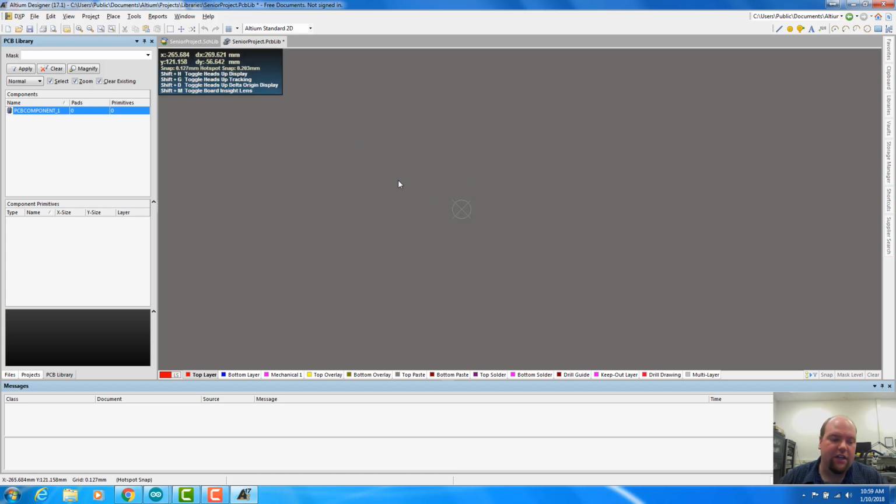And again, if you're gonna define something in millimeters, it's best to use millimeter grid spacing. Just keep everything metric or keep everything imperial, whichever one you're using. It's quite common to see PCB components that use one or the other. Don't be afraid of mixing and matching the two. Just make sure that if the part is defined using imperial units, you use an imperial grid for it.